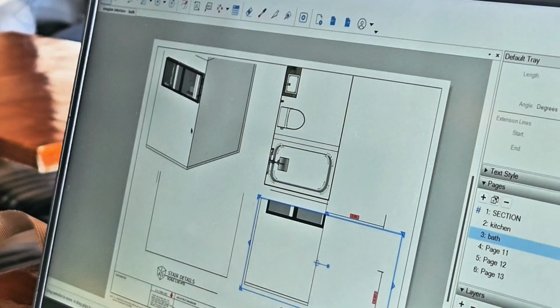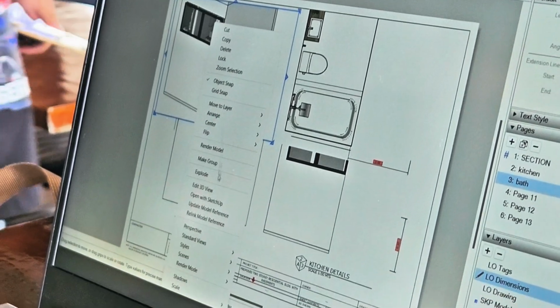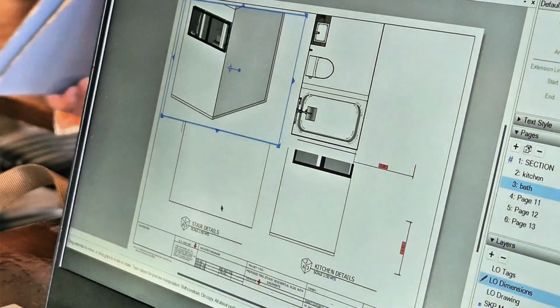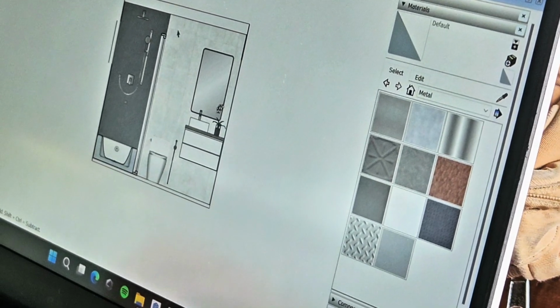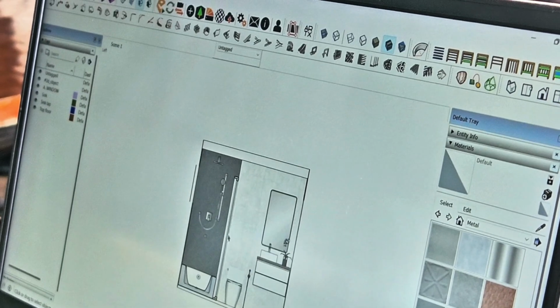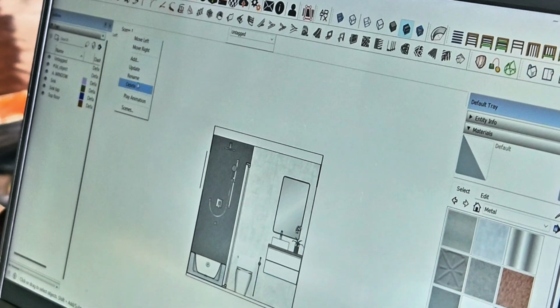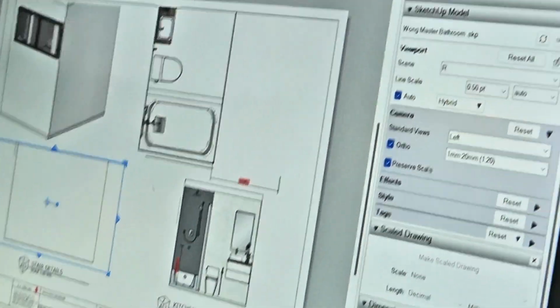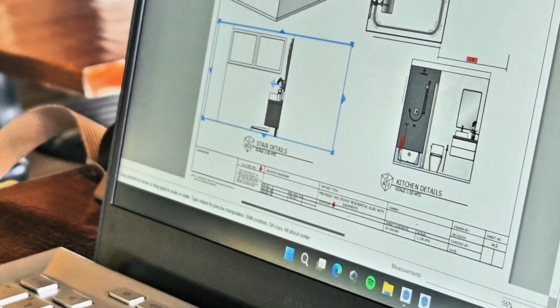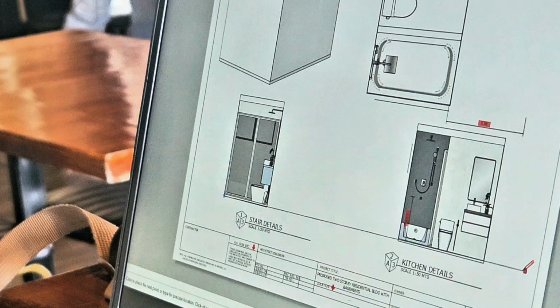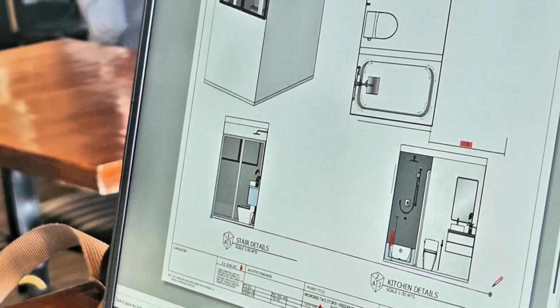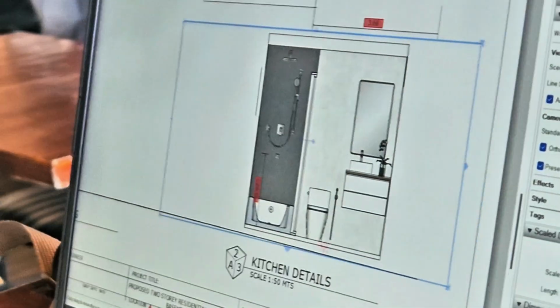Now, if you notice the isometry, there is a wall blocking it. So right-click and open with SketchUp. Shift-Q to place section and Shift-A to hide it. Shift-1 to create a new scene and right-click, rename the scene to front. Save and reload in SketchUp. Make sure to reset the camera views because it's now following the scene. Make it consistent by aligning the floors with each other. Use a simple line tool and press the arrow keys just to go down.